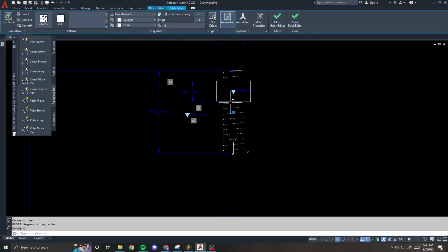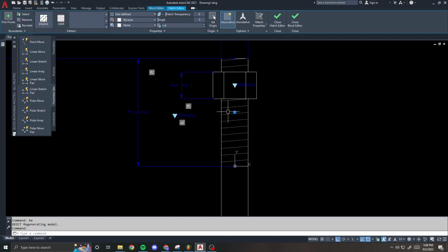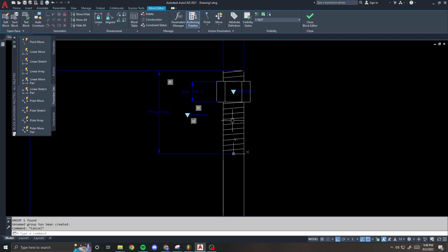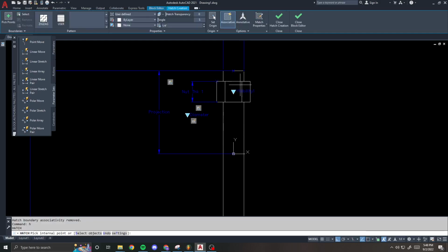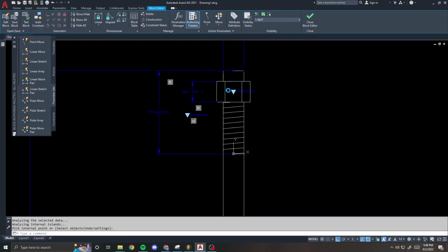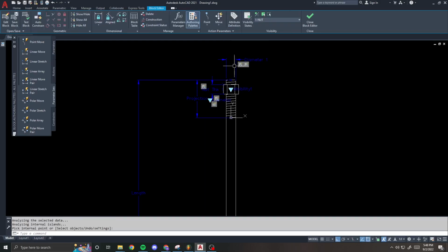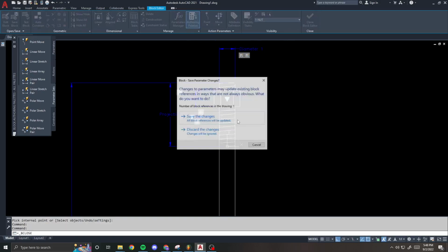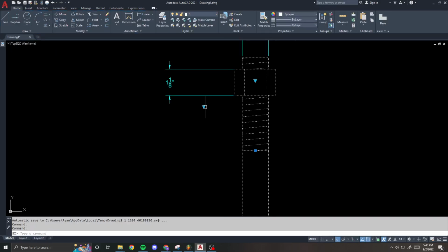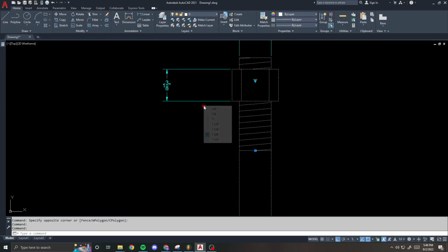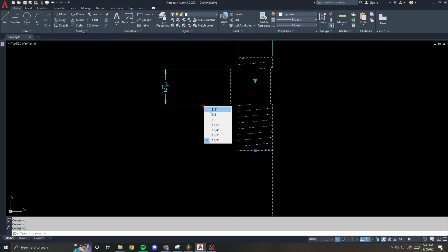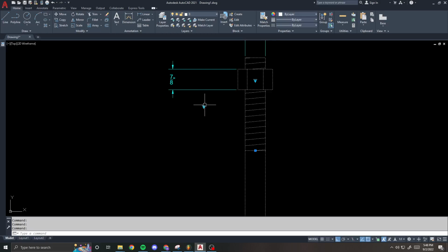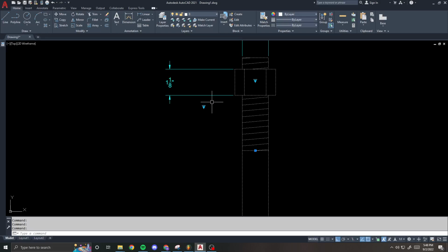And this can be a problem. If you need to separate these hatches out, you can do 2 hatches. Sometimes it may be better to do that. Let's actually not choose the hatches at this time. Let's see what happens. Remember I told you early on, I'm not sure if it's a good idea to click the hatches or not. And look at that. It was a better idea not to click the hatches because it's associative, so it's following whatever the border is. So perfect.